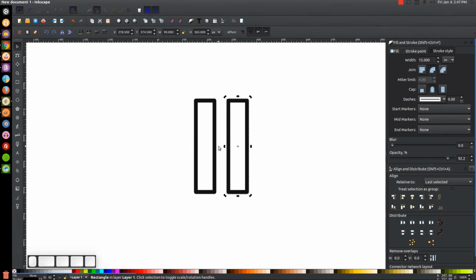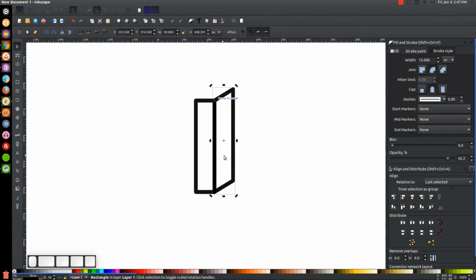And what I'm looking for right here is these sliding handles on the side. So I'm going to hold control on the keyboard and take this right arrow and slide that up a few steps. So I'll go 1, 2, maybe 2 steps. That's good like that. Then we'll take this corner right here and snap it onto that corner. So we'll just click and drag over there to snap that onto that corner.